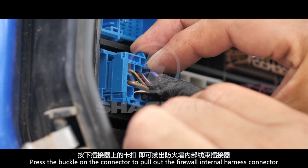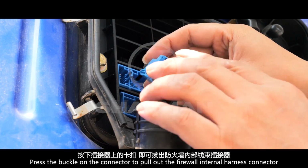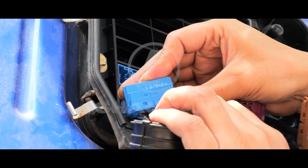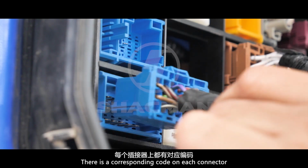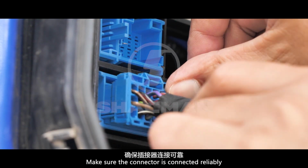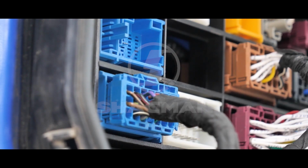Press the buckle on the connector to pull out the firewall internal harness connector. There is a corresponding code on each connector. Make sure the connector is connected reliably.